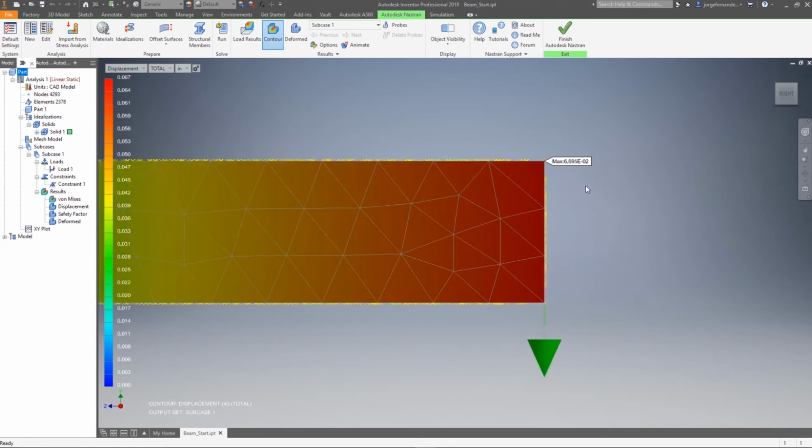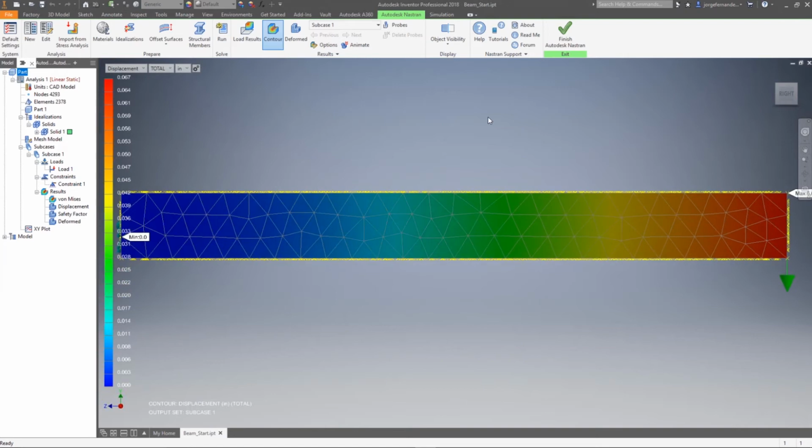Look at that, 0.0669. That's pretty close if you ask me. I'm not even going to calculate the margin of error on that one, right? Exactly. And I think we're using as the elastic modulus 30,000, or sorry, 30 times 10 to the 6th. In this case, we use like 29 times 10 to the 6th or something. So, I mean, just that change in elastic modulus probably gave us that. But yeah, definitely you want to be sane when doing this.